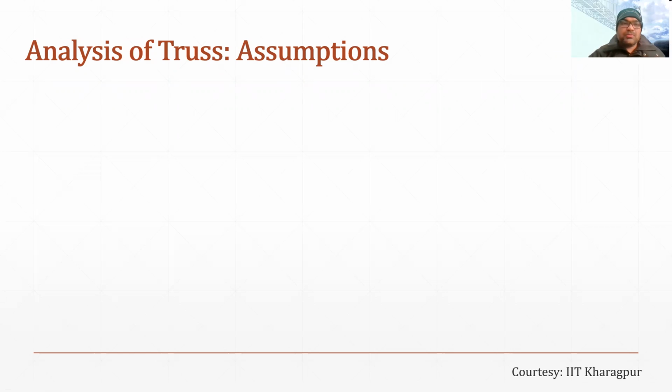Now, before we discuss this, first of all, I would like to say that if we want to construct a truss structure, then we have to design the truss. Designing the truss means we have to find out the size of the members which will be used to make that truss. To calculate the size of a member, we need to understand the force in that particular member.